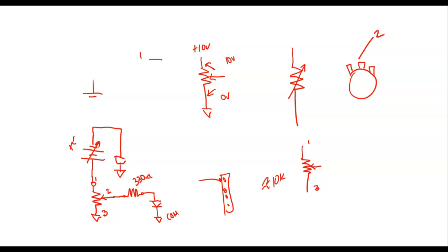What are resistors rated in? What 3 things is a resistor rated in? What 3 things? Next test. What 3 things are a resistor rated in? Watts, tolerance, and ohms. They are not rated in volts. So if I've got a 100K pot and it's rated at 10 watts, if I put enough current through there to make it do the watts, it's going to burn up.